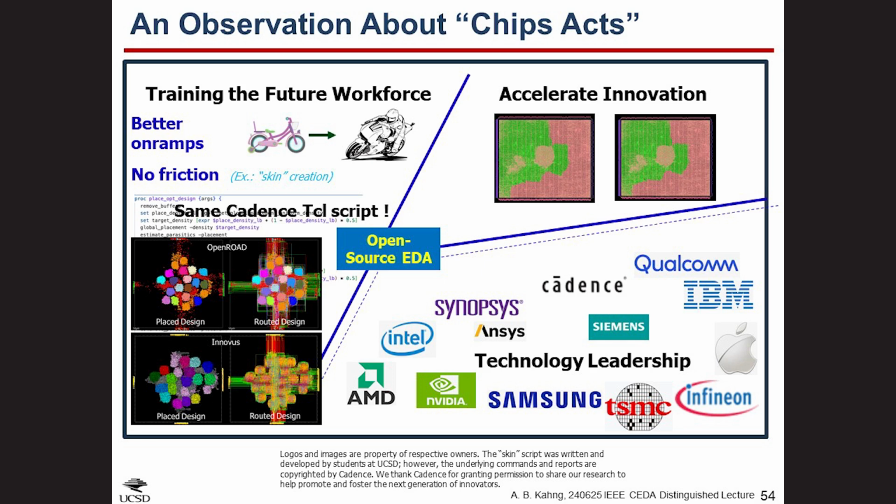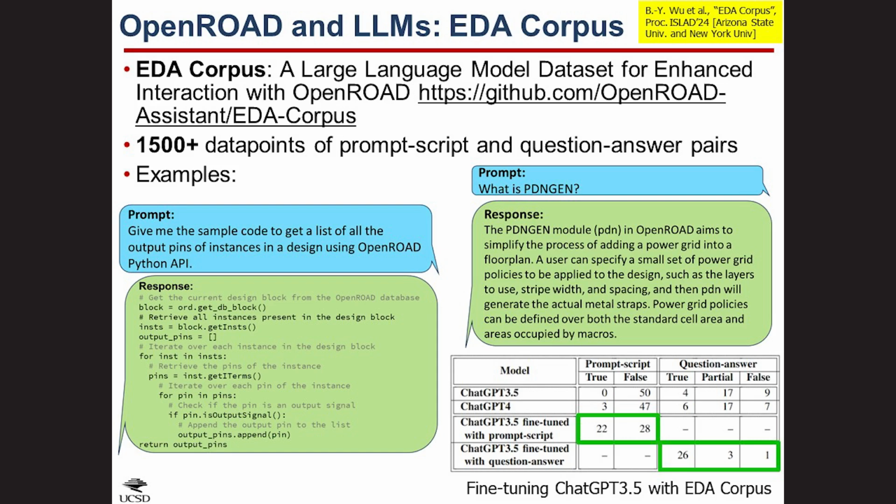And here we can specify hyperparameters and sampling ranges in a JSON file. AutoDMP uses a form of multi-objective Bayesian optimization, tree-structured Parzen estimation, to generate candidate placements. We use OpenROAD Router's resource estimator and congestion mapper to assess the placements during this step. Step 2: run the Innovus PNR flow on the best 5 candidates. The best PPA is achieved by run ID number 14 out of 29, I think.